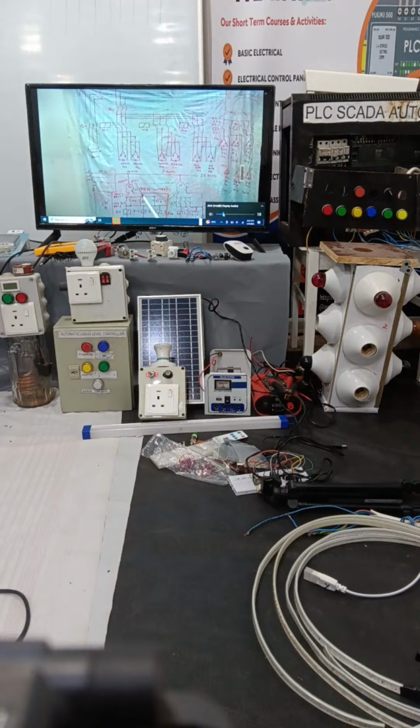In manual mode, when the switch is turned to the left, the supply comes here, then it passes through a stop push button, or open push button. It will have a normally closed contact. Normally closed means in normal condition this contact always remains closed. And this is one closing push button, a normally open contact. These are all spring operated. So when you press this, the current comes here and this contactor gets supplied. But when you release this push button, the contactor goes off.